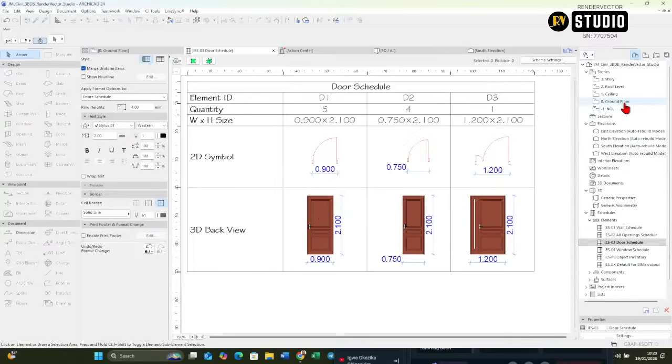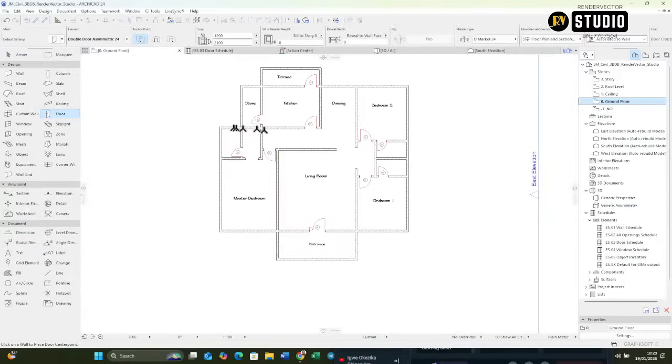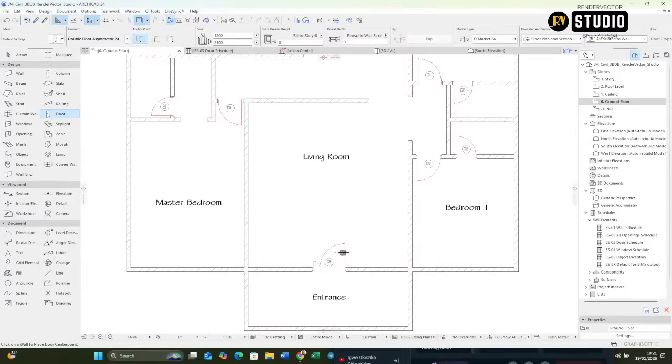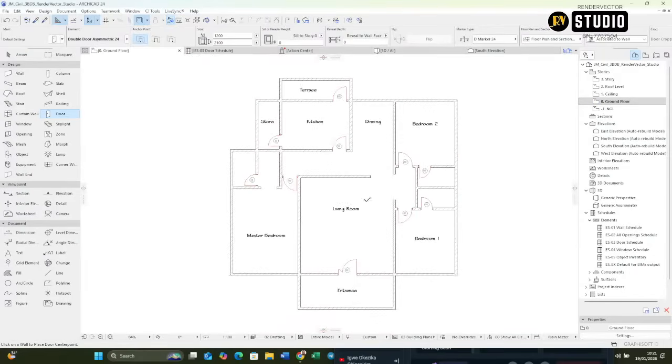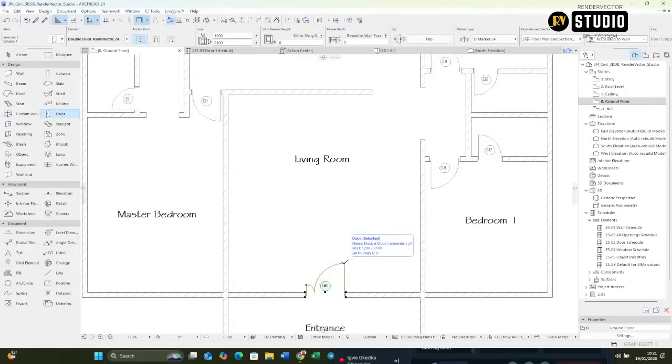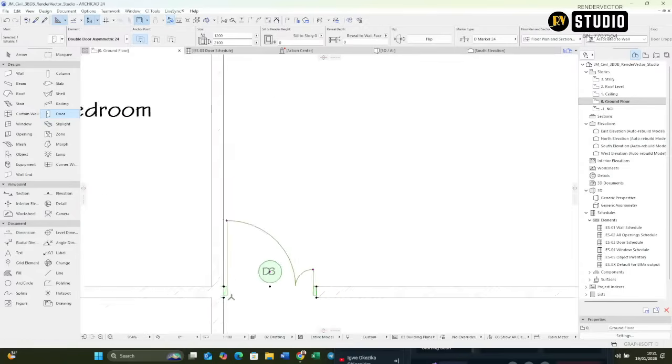So now going back to the ground floor plan, personally, I'm going to adjust this thing. You can't just enter my house and see my dining and all this. So I'm going to Control M, twist to mirror. Mirror this like this. Drag this one here.